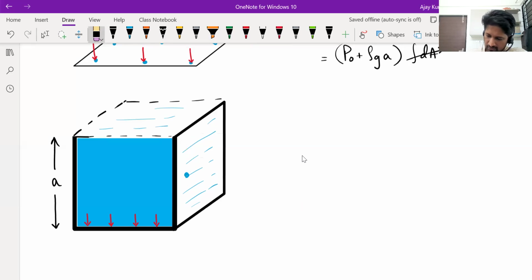So the force vectors, the dF vectors that you show, should be like this. Close to the upper surface, the forces will be weak. As you go deeper, the force becomes stronger. Close to the base, it will be the strongest. I should not say on the base. This is on the wall itself, but close to the base, the forces will be the strongest.